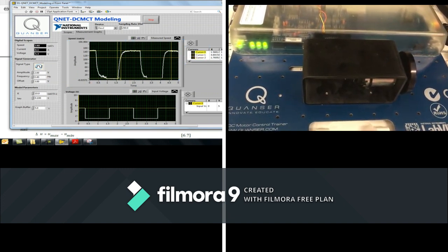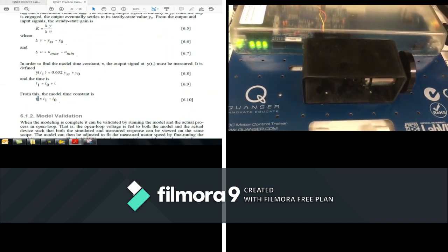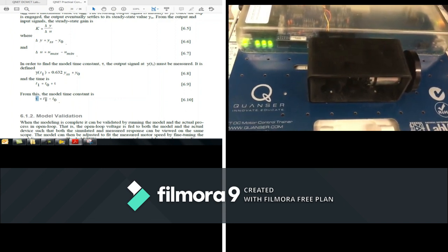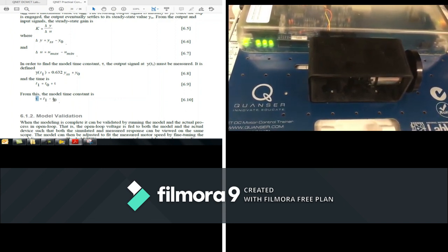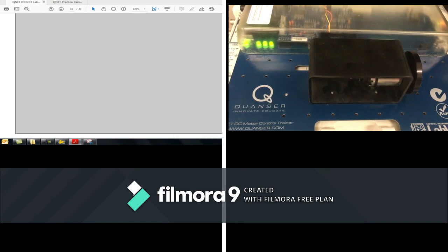1.56 for T0. Delta T will give me the equation. So in order to find tau, the time constant is simply the difference between T1 minus T0, and that's how we can find our time constant. That's it. So if we go back to exercise number 2